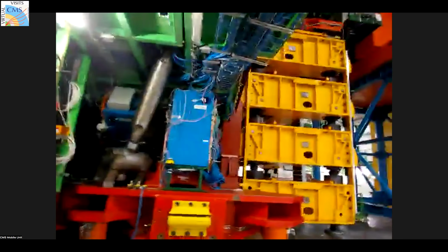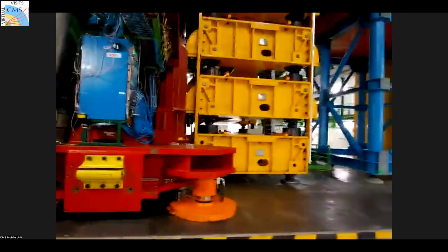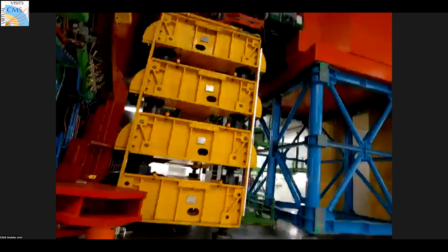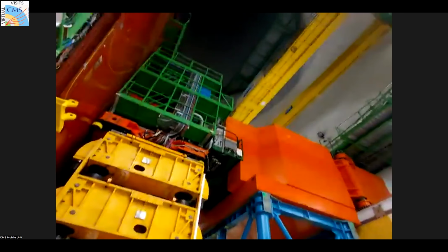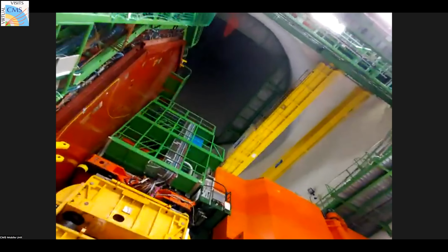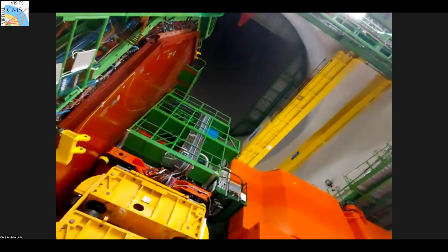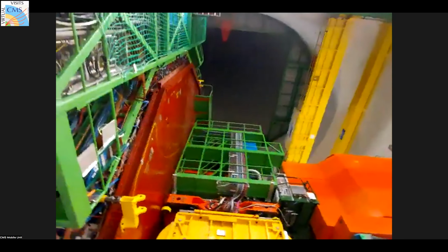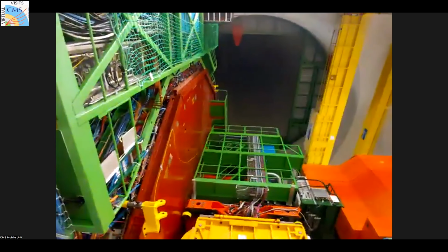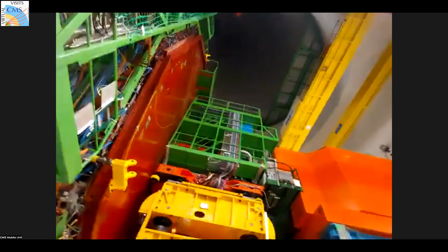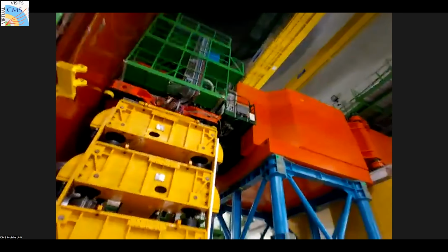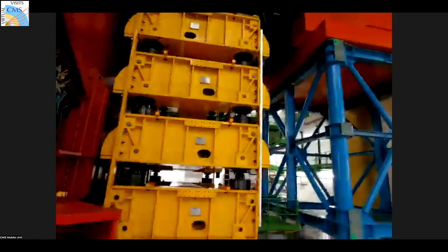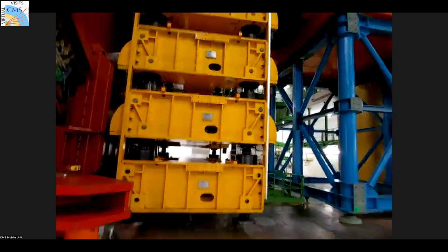But in steel production, manganese is an additive material that you cannot miss, and that creates manganese-54 that keeps radiating after the detector is switched off, in a decaying way. Of course, we are not talking about a nuclear power plant or a nuclear blast, but this is something that we can measure, and we have to keep it in mind when we access the detector.